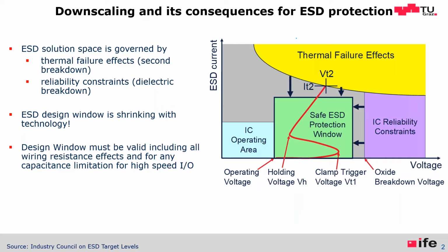And of course, if the speed is high, we cannot put a large capacitance there. So 1 picofarad is probably way too much. We talk about ESD protection structures in the external TVS diodes which are below 1 pico, like 0.5, 0.1 pico, or even lower devices exist. Now, why do we need to do this?